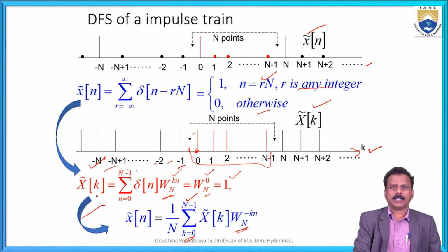Okay, here X of k is the discrete Fourier transform, where the twiddle factor is W_N^{kn}. But in the IDFT, the inverse discrete Fourier transform, it is followed by x of n equal to 1 by N, the summation k equal to 0 to N minus 1, X of k, the twiddle factor. Here the polarities are changed, minus, because of the inverse of the DFT.